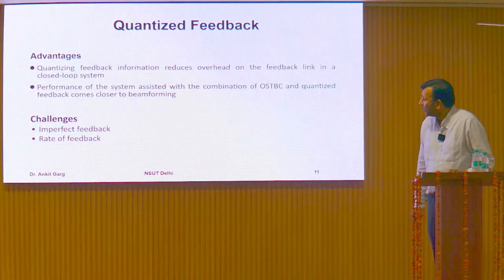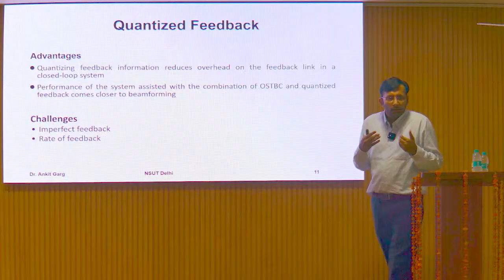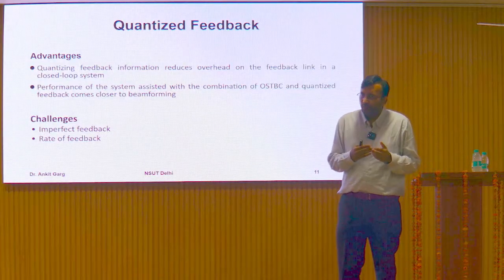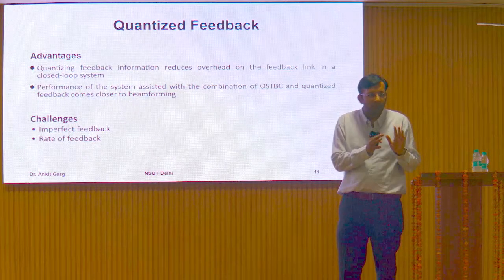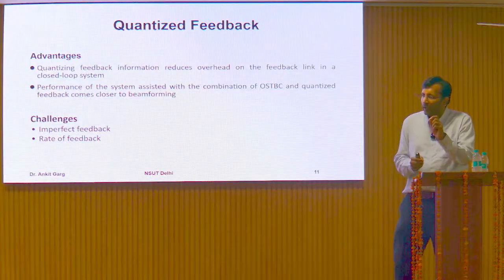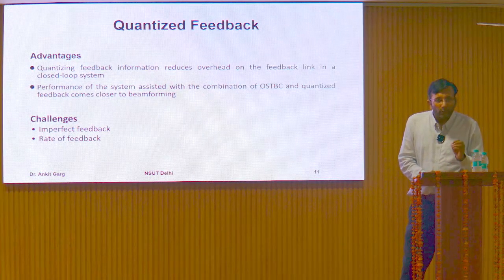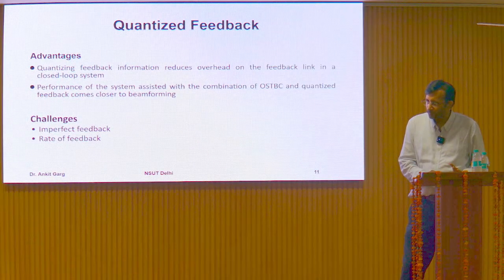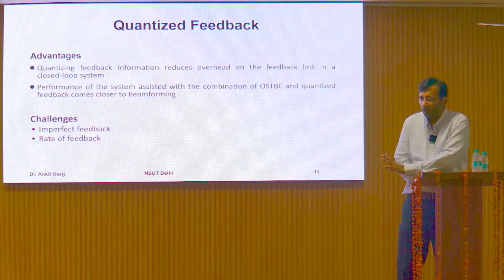So through this, the advantage is that we don't need to increase the feedback overhead to provide the full channel state information. See, channel state information means values of the channel coefficients. Values of the channel coefficients are complex numbers, x plus iota y, that I am going to display through the MATLAB code to make you understand.